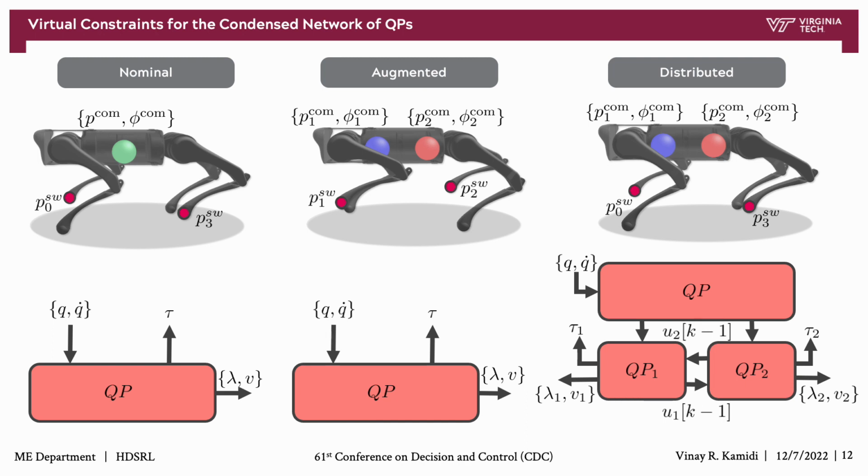This is indicated on the figure to the left. The 12 virtual constraints here would involve the position and orientation of the body frame and the Cartesian position of the two swing legs. However, this would not result in uniquely separable virtual constraints for the two distinct subsystems when decomposed. In order to accommodate that, we choose an 18-dimensional output function for the centralized framework and call this